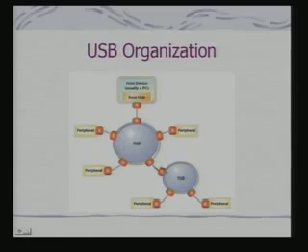The basic organization is what is called a hub based organization. So, you have a host device. To a host device you can connect a hub and your peripherals get connected to the hub. Otherwise, you connect a single peripheral with the host device. So, I can now build a tree. If I connect another hub at one port, I can connect more peripherals to this, and that is why this is called a bus. That means there can be multiple devices hanging from one link.